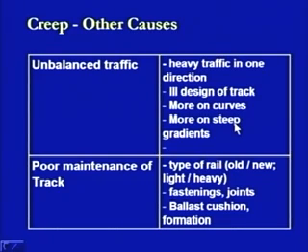The steeper the gradients, the more force is to be applied in the forward direction to move the train on these gradients, or if the train is coming down grade, then more application of brakes will be there, and due to both of these reasons there will be creep in the rail.